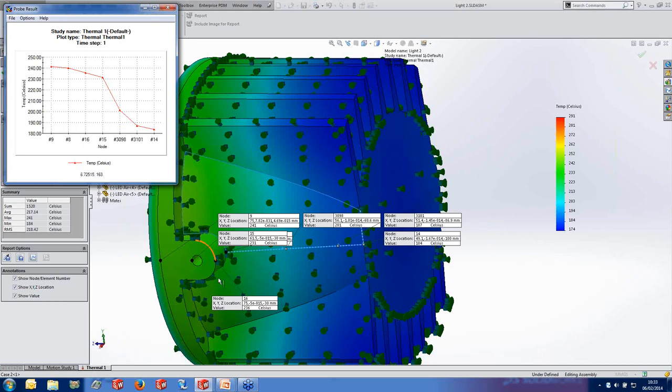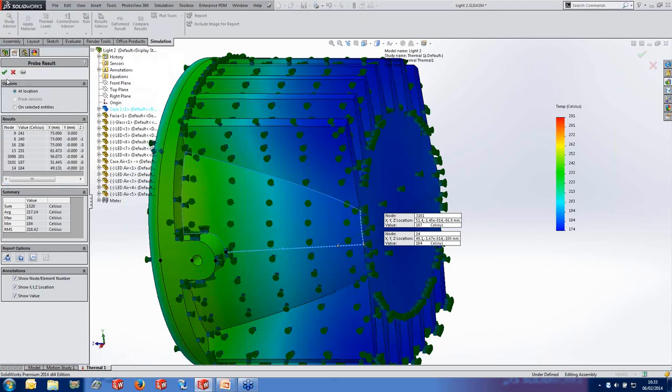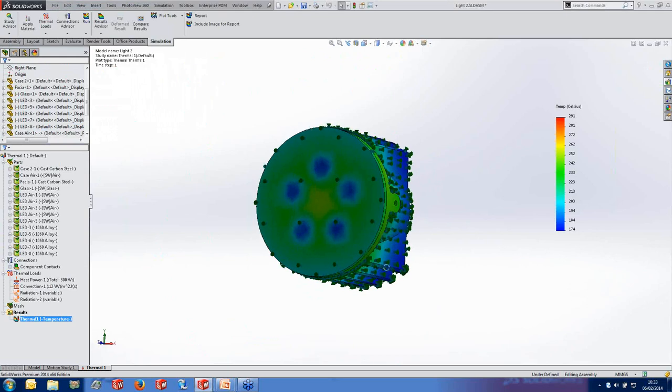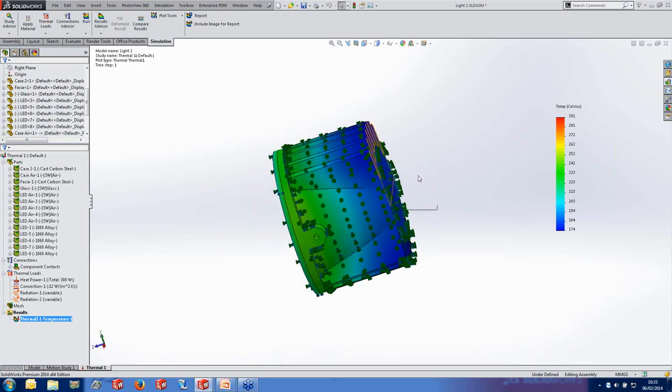These numbers down here are the node numbers. They are essentially meaningless. It's just how SolidWorks has broken up the model, but to a user getting temperatures out, they are just positions. So we've got temperature against the node number there. So we can start to get more information out and take this on for other tasks. Potentially we can see the heat out of here, which would enable us to tell what's happening with the frame that this might be attached to, for example.